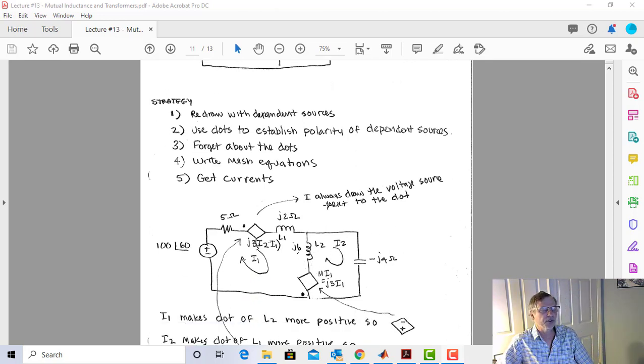First thing I'm going to do is draw that voltage source between the inductor and its dot. Now there's no real good reason I do that. I do it because that way I can do it the same every time, but I'm going to give you a little better reason for that several examples down the road. So I draw my voltage source between the inductor and its dot, and all I do is draw the diamond. Here I need another diamond. Here's the inductor. I squish the dot out a little bit and I put the diamond in there. Next thing I'm going to do is put in the value of the source.